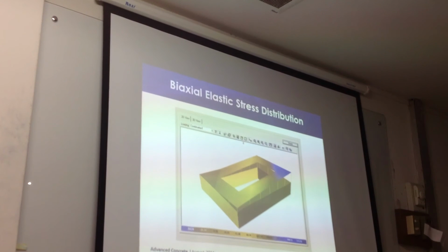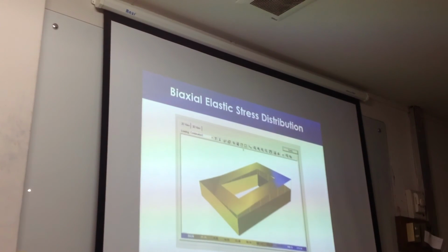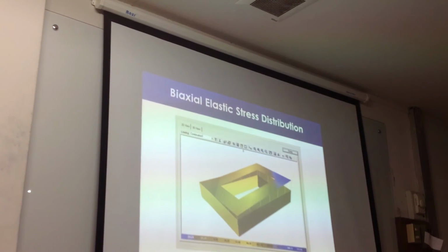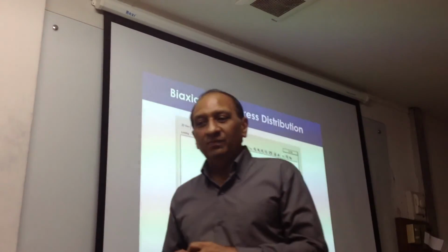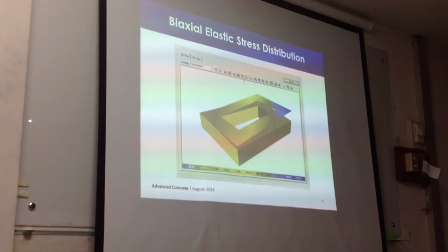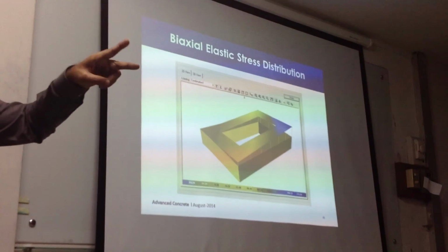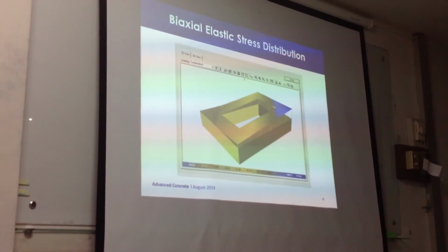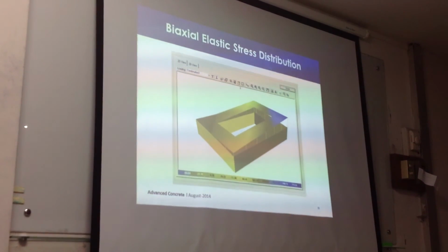What if there is only moment and no axial load? In that case, it will be 0. It can be 0, depending on the moment value, right? So, sorry, neutral axis depends on moment and axial load, both of them, right? Both of them have to be there. That is why when we're dealing with beams, when there is no axial load, the neutral axis depth is defined by only the moment value. It can exist over there, and the two forces are self-balancing. So the net P is 0, always. The compression and tension must balance, and must be equal to 0.